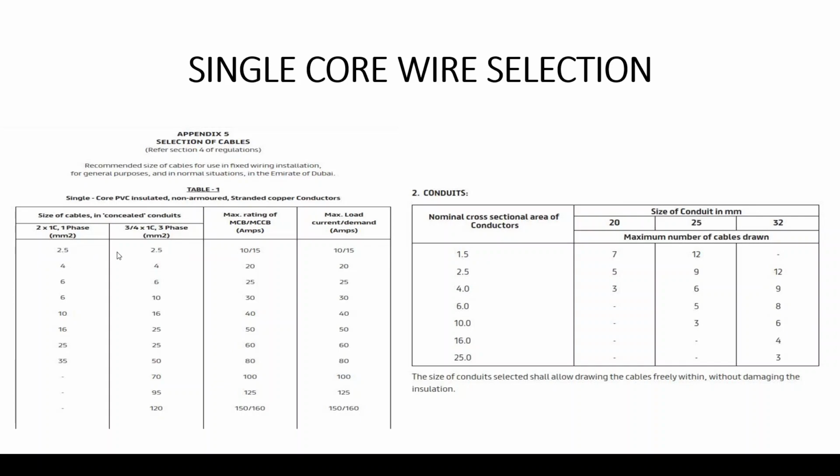How many do we use? As we explained in one of our earlier videos in detail on the load schedule, you use 3 wires for each circuit. You have the live, the neutral, and the earth. All of them are 2.5 mm. Then another example is a 20 amp breaker, which is a typical power circuit. You would use 4 mm.